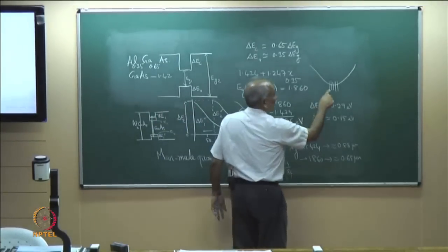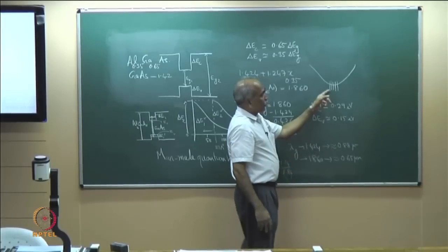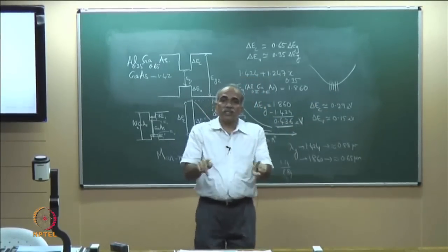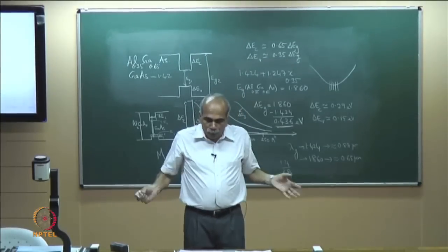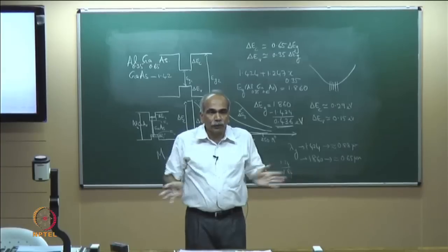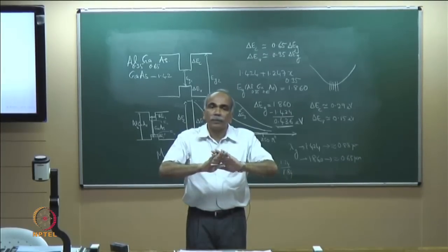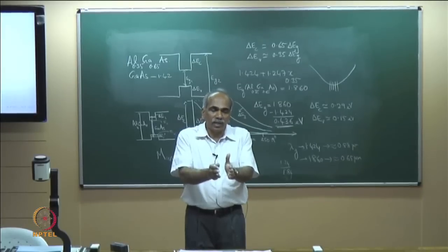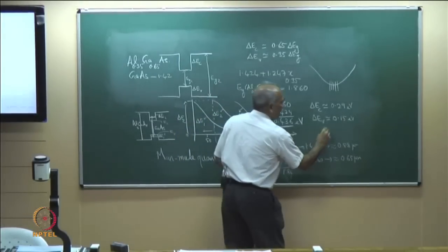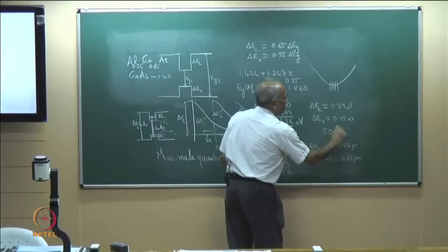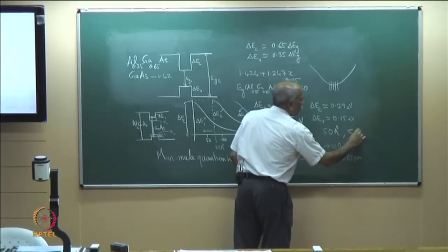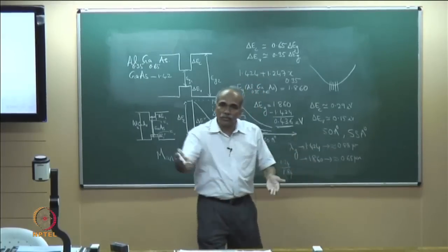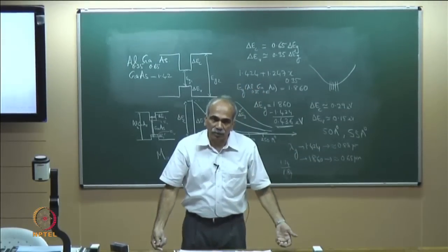Therefore, tuning, that is changing the emission wavelength by controlling the thickness, is the easiest way, because the composition, the gas mixture and gas flow rates in the fabrication process are kept constant. Simply the thickness is controlled. In one case you may have 50 angstrom, and for the next layer you may take 55 angstrom, 60 angstrom. So you change the thickness by 5 angstroms and the emission wavelength will change.